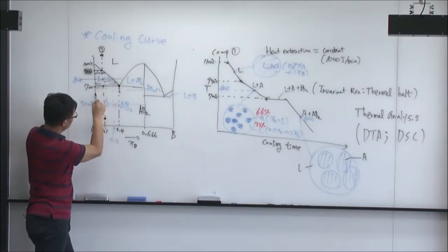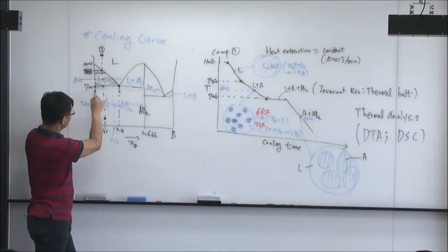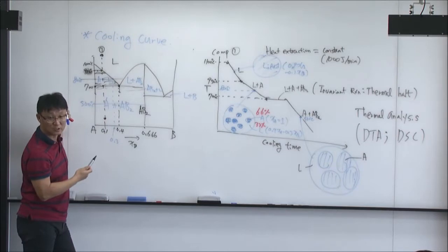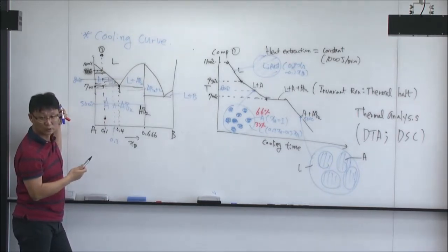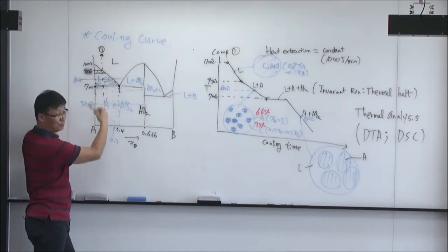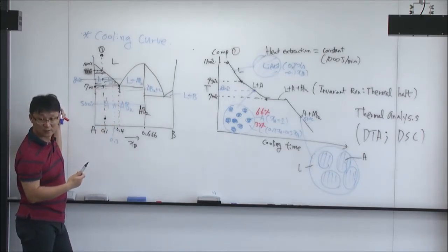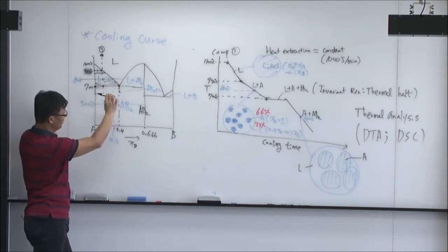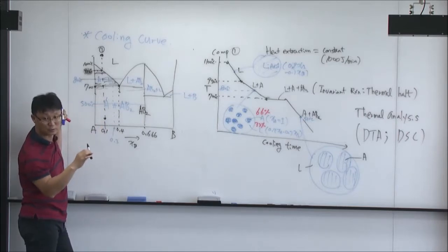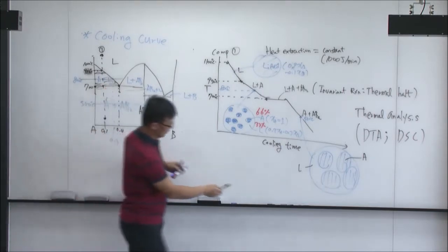This liquid becomes this solid and this solid. And the previous solid is just solid as it is. It's not changing. Okay? So we have actually two kinds of A phase. A which was existing before the eutectic reaction, and A which is forming from the liquid phase during the eutectic reaction. Do you understand? So when you have the invariant reaction, it's a little bit complex to draw the microstructure. So just above this eutectic reaction, you have this kind of thing.